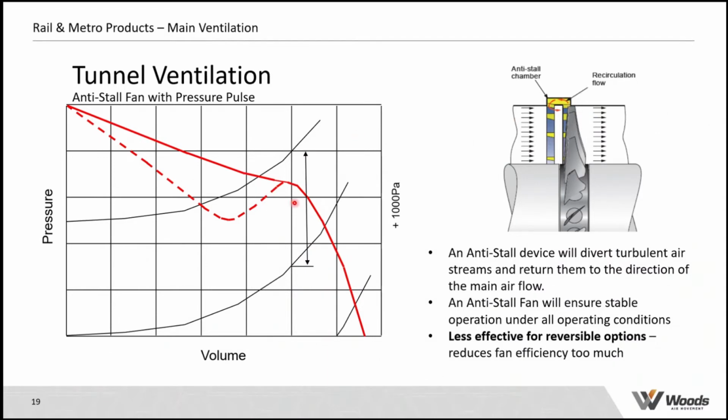And what you end up with is this dotted red line here, which represents the normal fan curve, showing this sort of stall. But the performance curve carries on and keeps going up, and this stall situation here is greatly reduced. Again, the stresses on the blades are reduced, and therefore it becomes a safe operating condition for the fan. It won't cause any damage to the fan.